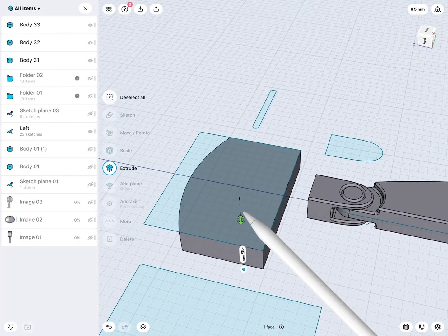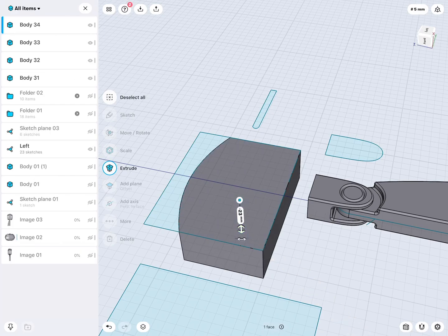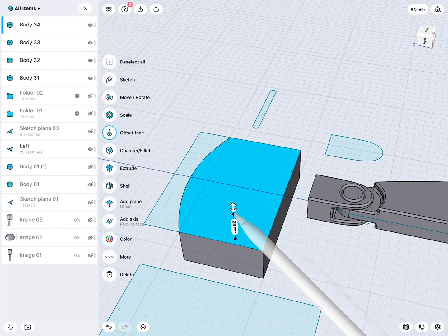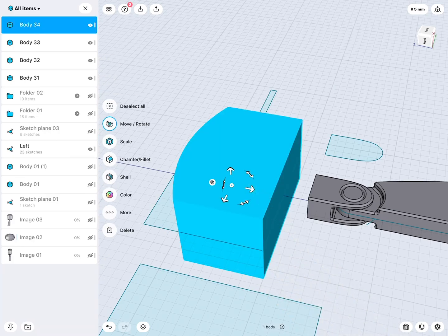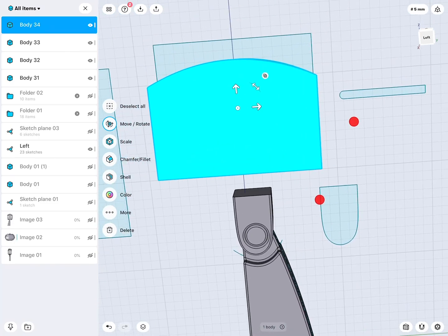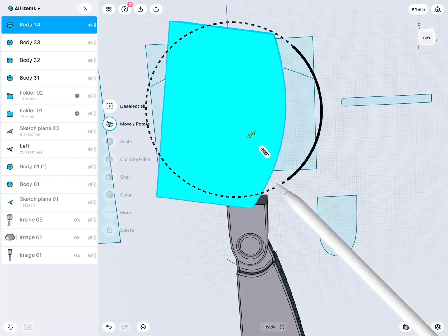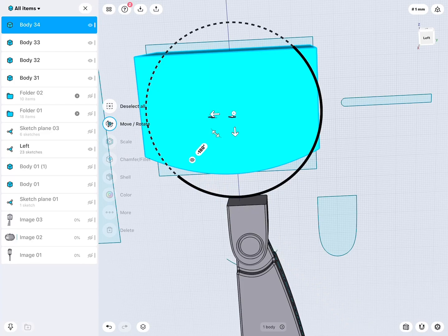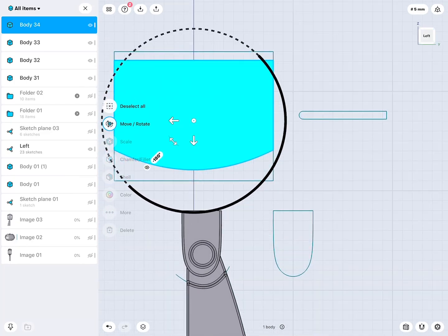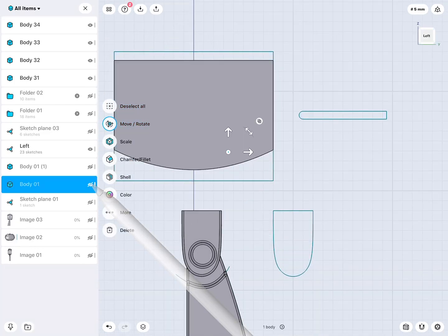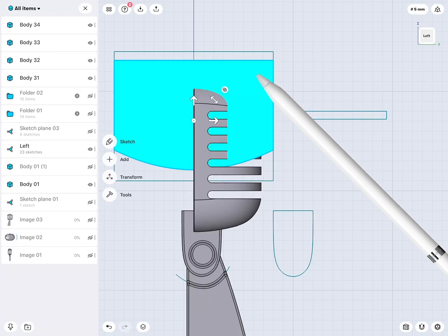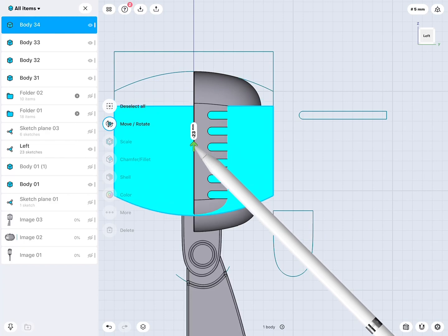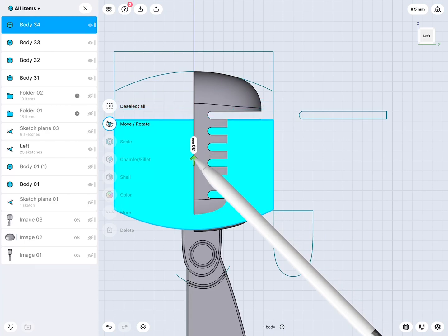This now I extrude down 23 and 46, double tap this object. Now I rotate 180 there, and then with this visible, this object I slide down till it matches up.